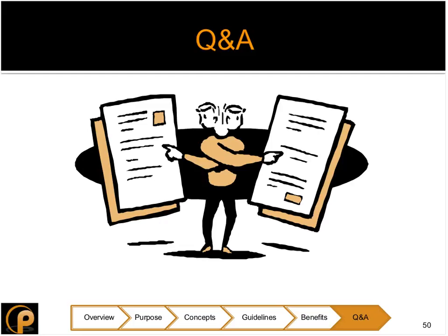So the first question, are burst disks acceptable as a PRD? Yes, bursting disks, also known as rupture disks, are considered an acceptable pressure relieving device. However, there are certain considerations that have to be made before you choose one.